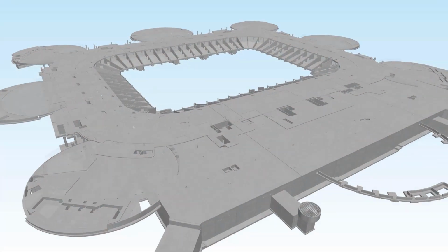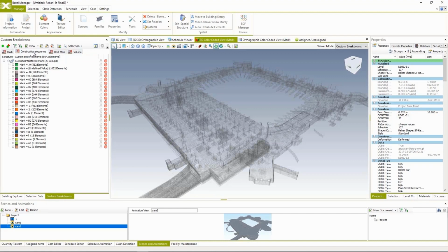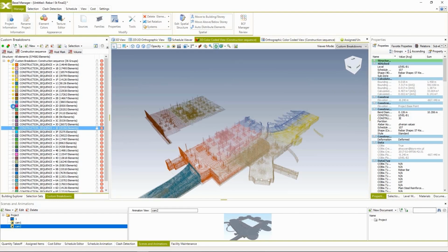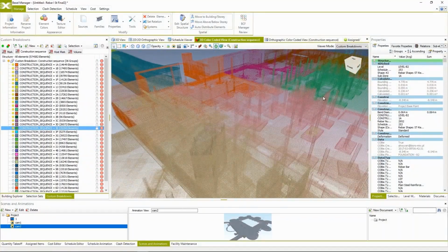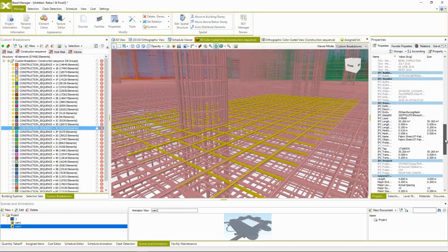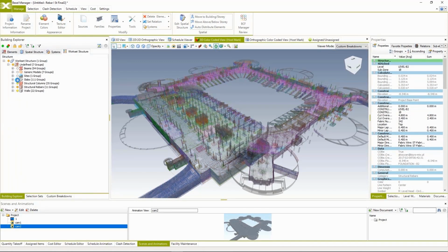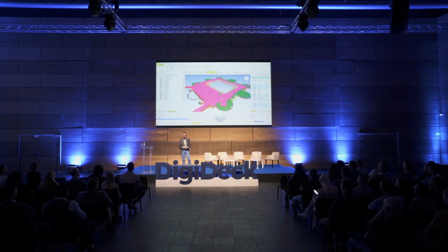One of the first things we needed to do upon receiving these BIM files was checking their content, compliance with the naming convention, and performing different BIM checks related to the information or properties which are built into these 3D elements. For these purposes, we mainly used BEXEL Manager, our platform, and Solibri for geometry control, with BEXEL Manager for property and information control. One of the benefits was that we were able to color code these elements based on different properties, as you may see here for structural concrete slabs or reinforcement.